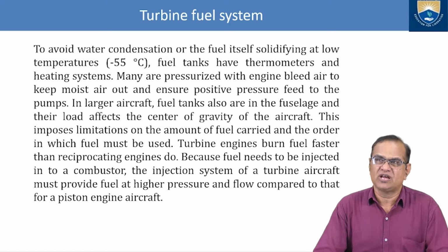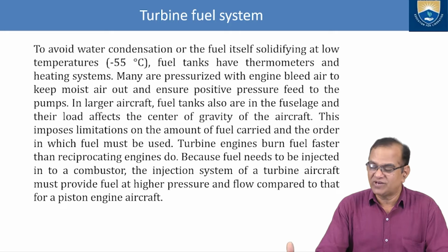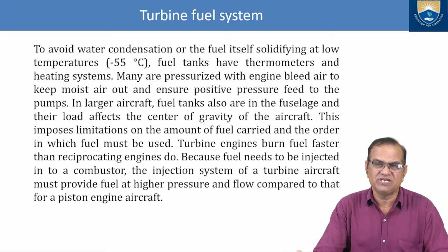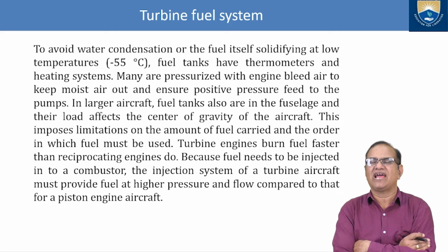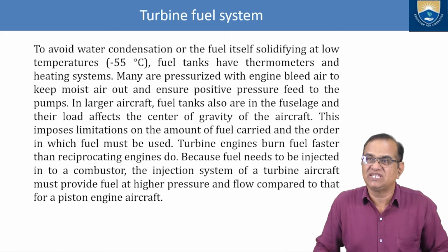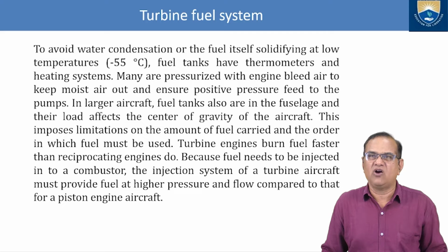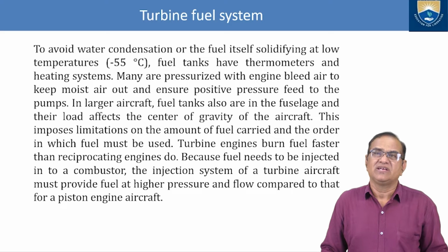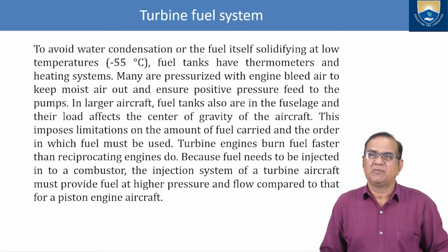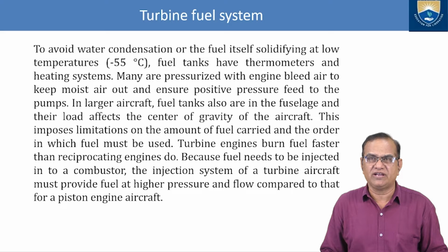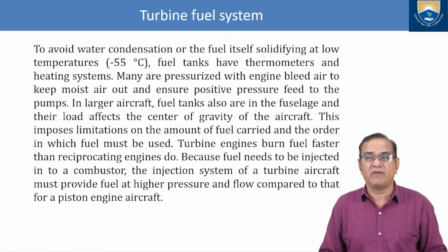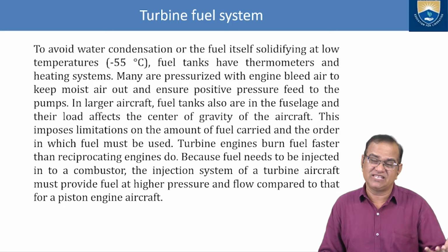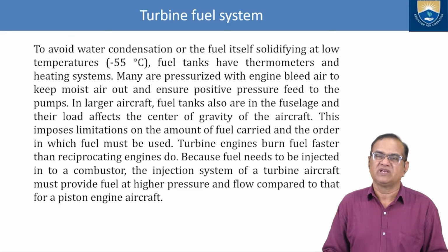Fuel tanks have thermometers and heating systems. So the fuel tank itself has a thermometer and there is an electrical heating system, and this will try to heat. Many are pressurized with engine bleed air to keep moist air out and ensure positive pressure feed to the pump. Some of the tanks are pressurized from the bleed air, which is hot air, so that the atmospheric air will not enter, which makes sure of positive pressure feed to the pump. The atmospheric pressure is lesser than the inside, so the air will not enter.